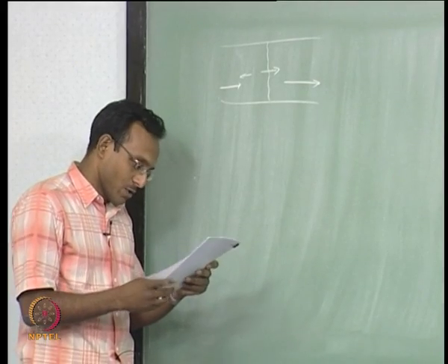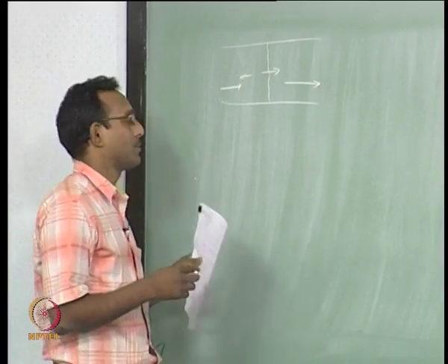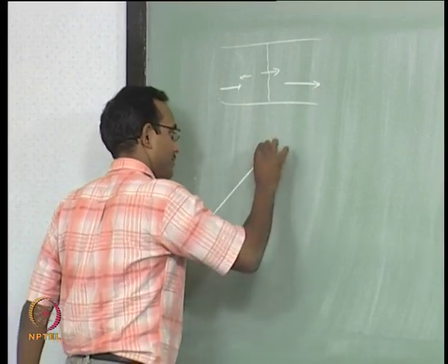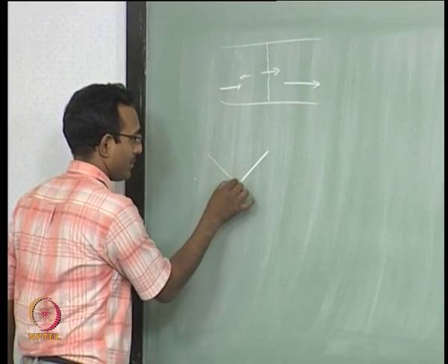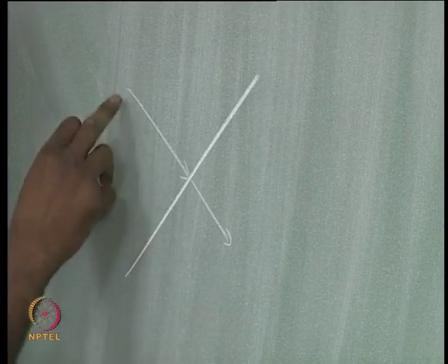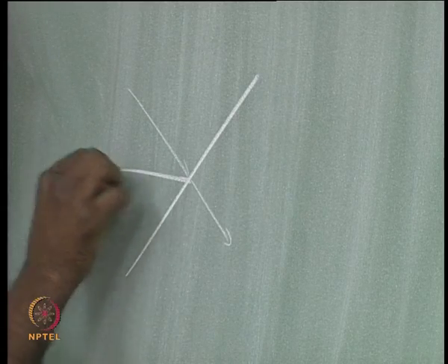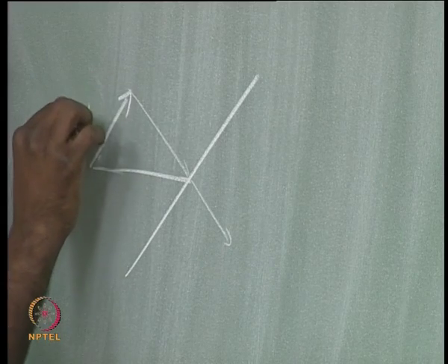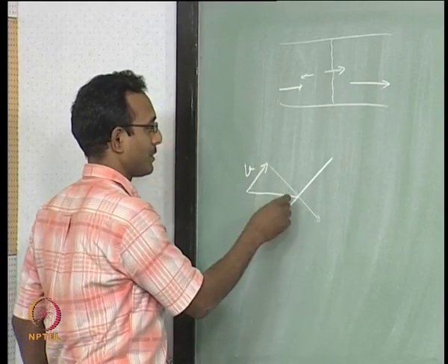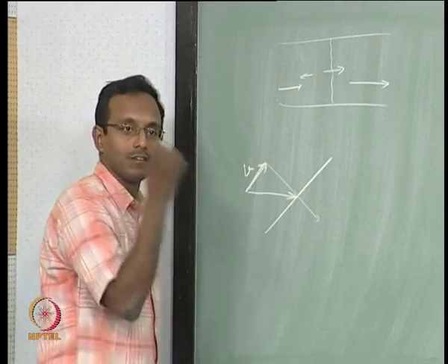Okay. Now we want to derive this in 2 dimensions. We are going to take a similar approach like we did for the oblique shocks derivation, where we said if there is a wave, I am going to look at the normal component and how it changes. I am drawing an oblique shock picture here though. The arrow lengths are changing that way, and I am going to say that the actual velocity is this, and we have an observer moving along the shock this way, that with respect to that observer the flow field looks like this, right.